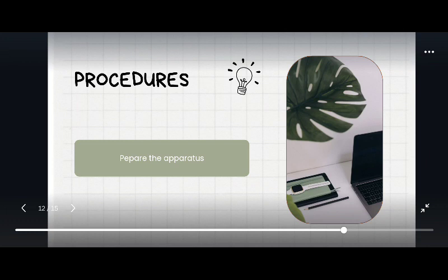Adjust the liquid limit apparatus by checking the height of drop of the cup. The point on the cup that comes in contact with the base should rise to a height of 10 mm. The block on the end of the grooving tool is 10 to 13 mm high and should be used as a gauge. Practice using the cup and determine the correct rate to rotate the crank so that the cup drops approximately 2 times per second.